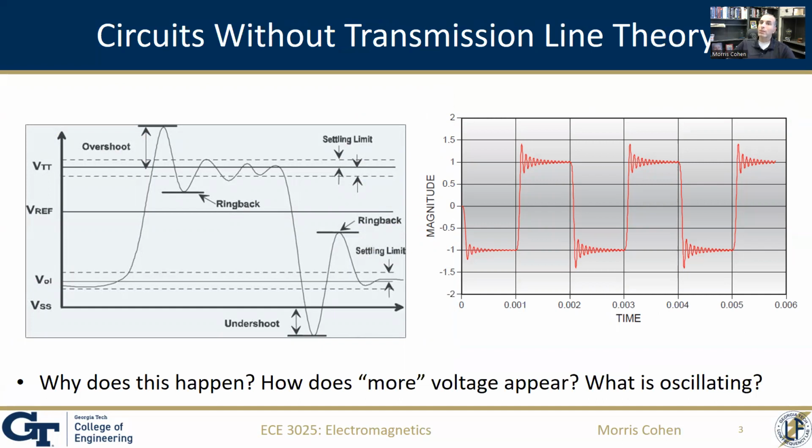And you expect it to remain clean, but maybe at some point you touch your oscilloscope to a different place in a circuit, and you see this weird thing, what you see on the right, where instead of having a nice, perfect brick wall, you have the signal kind of overshoot and oscillate back and forth until it settles out. And then when the signal rises again, you see the exact opposite, where you see this overshooting and gradually approaching where it is that it needs to go.